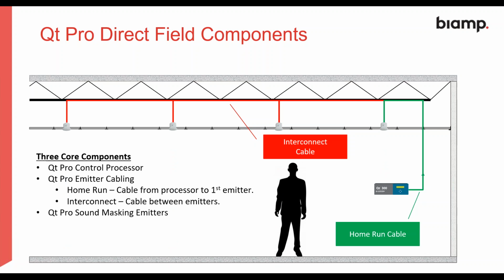Now all these cables that we use in our systems are category 3 or above cables. So they're just standard Cat cables. We normally use Cat 5 in Europe. We can use anything from Cat 3, like I say. The reason why Cat 5 is used more is it's quite flexible, and if we get up to Cat 6 or 7, they can be a bit stiff, really. We do not need to have screened cable, just a normal cable, but we do need all 8 conductors on the cable.